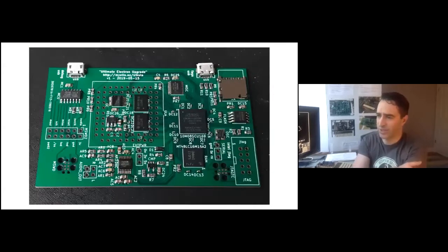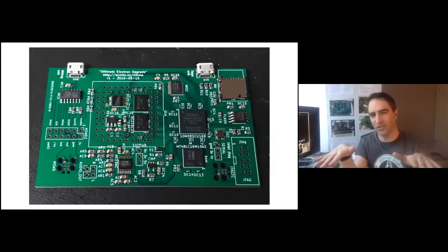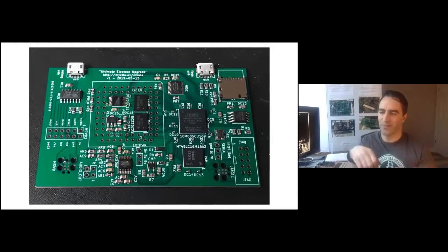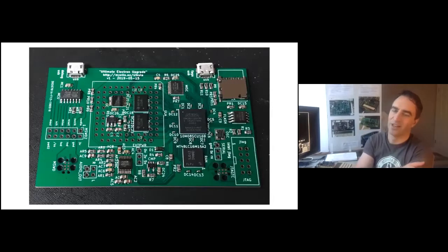Here's the actual board with all the surface mount components soldered. Took about 2 hours. For stenciling, you put the circuit board down on the flattest surface you can find. There's a stainless steel stencil which has been laser cut with little openings for where the solder should go. So you very carefully orient it over the top, squeeze some solder paste on and squeegee it over. Very carefully take it off, hope that you haven't made a mess of it. Place all the components with tweezers, and then you put the whole thing, ideally in a surface mount oven, but I just put it on a hot plate.